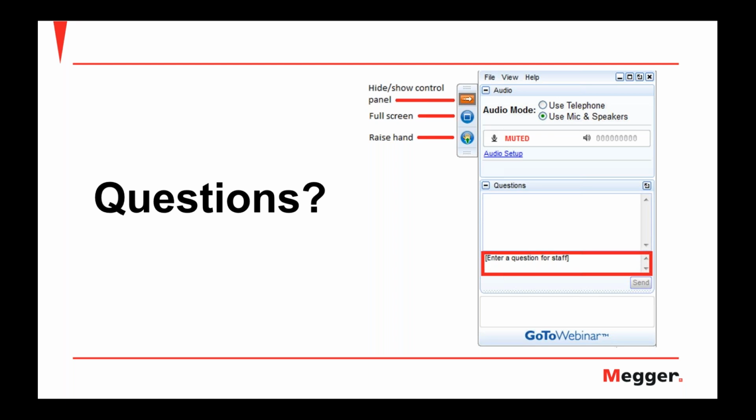Okay, awesome. What should be the specific gravity value for a battery, and what are the routine checks? The specific gravity is going to vary based upon the battery, the battery chemistry and the manufacturing. So really you want to look at any installation guide or the data sheet of a flooded cell, it's going to have that information in there. That's critical information to know.